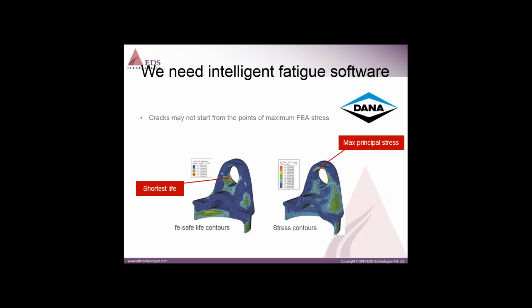So when it comes to more complex loading, the correlation becomes lesser, and between the stress plot and life plot there is a danger. It is also dangerous to assume that the high stress points are the ones where fatigue cracks start.